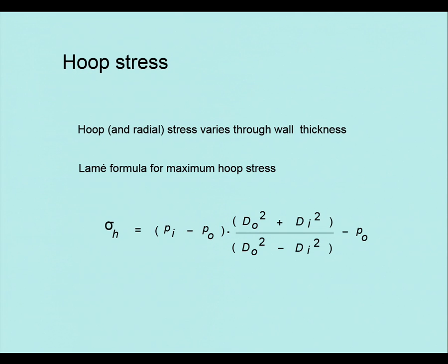So, as often in design houses, they won't bother with the normal Barlow's thin wall theory. We'll just use thick theory, because that will give you the actual stress.